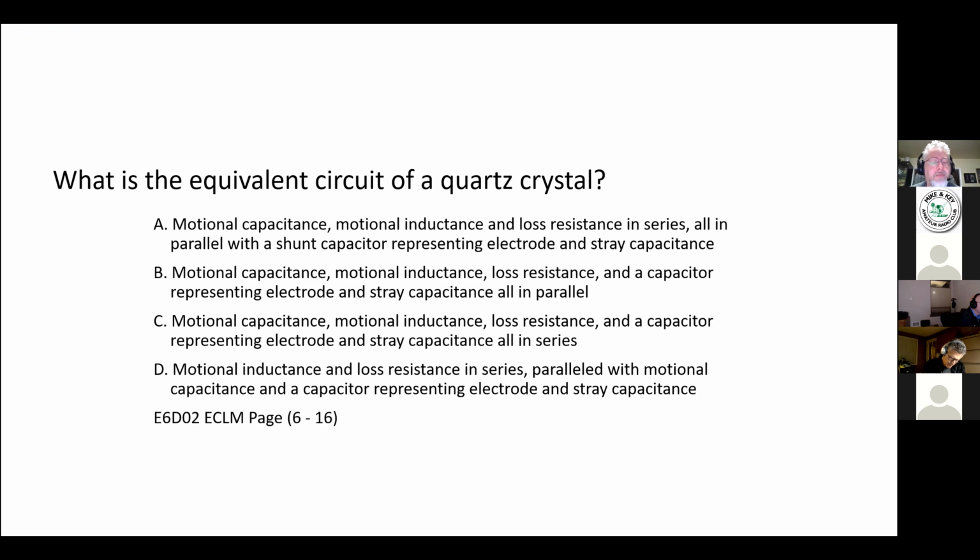Or C, the same elements all in series. Or D, motional inductance and loss resistance in series, paralleled with motional capacitance and a capacitor representing electrode and stray capacitance.